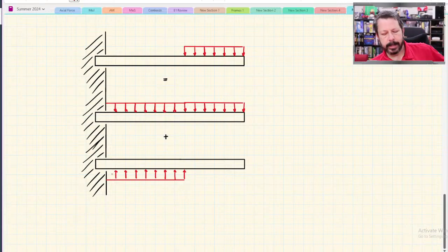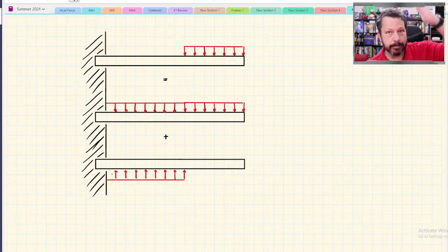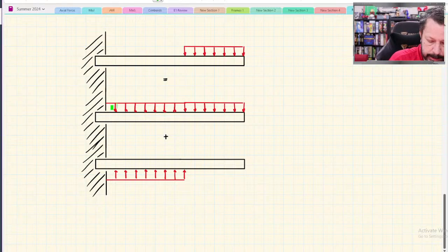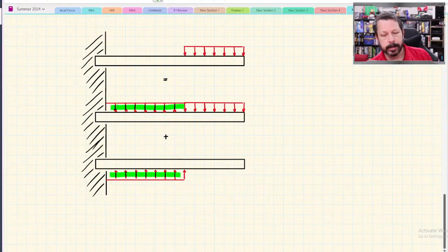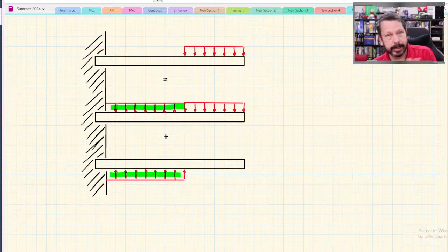You could think about it as adding a distributed load that's pushing the beam back upwards to counteract all of this section. These two would basically counteract each other, and they would leave you with only the part of the distributed load that is at the end of the beam. Or you could say, instead of a plus sign, you could do minus, and then you could put the distributed load on top like you normally would.